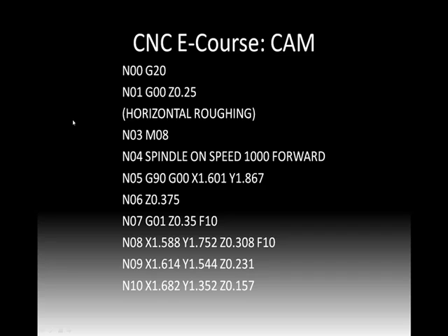You'll see on the left-hand side, those are the line numbers. Some post-processors spit them out, others don't. I like it just to keep track of it. And this is, keep in mind, a very small snippet of G-code. But as you read through it and you get used to G-code, the more and more you see it, it's telling the machine to do very specific things.